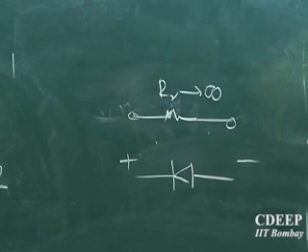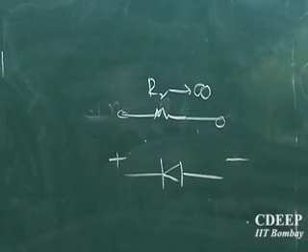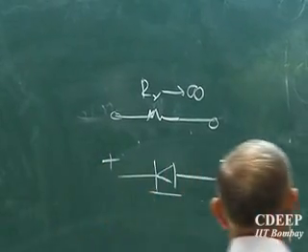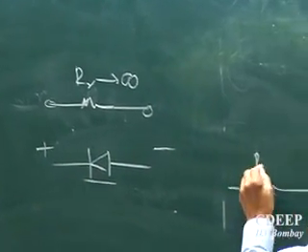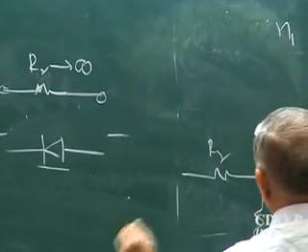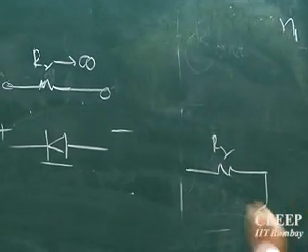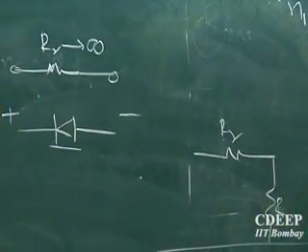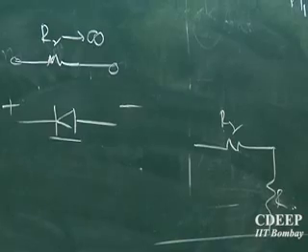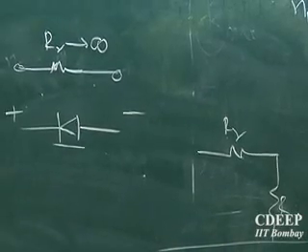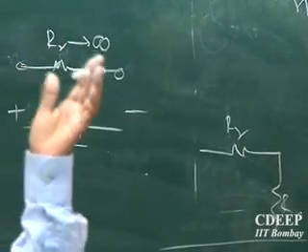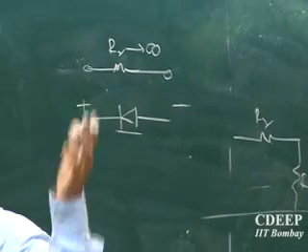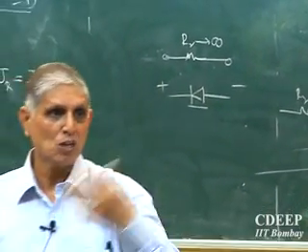So we figured out in a circuit, wherever the diode is, let's say the diode is reverse biased and there is something equivalent of this appearing, if this R is comparable, this will reduce the output voltage. Is that clear? If RR is not very large, as it may happen at larger voltages, then in a circuit it may actually reduce the voltage.